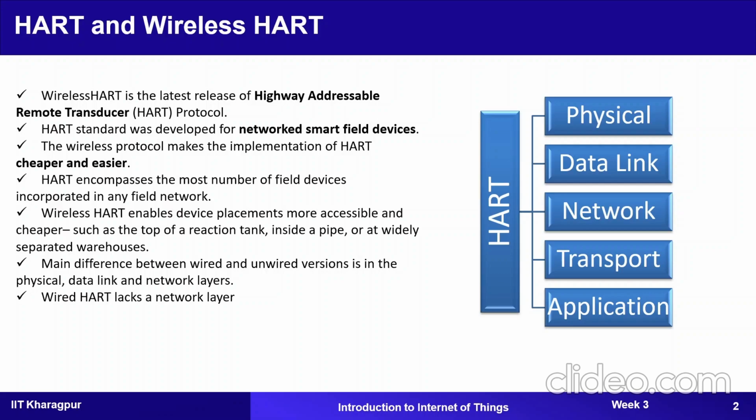Now the congestion control in HART. Interference-prone channels are avoided by using channel switching after every transmission. Okay, so basically in case of HART, what we do is we do channel hopping continuously, or after every transmission. So what happens if there is a particular channel in which there is lots of interference, then due to this channel hopping, this interference channel is going to be avoided.